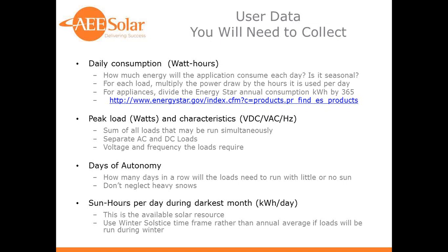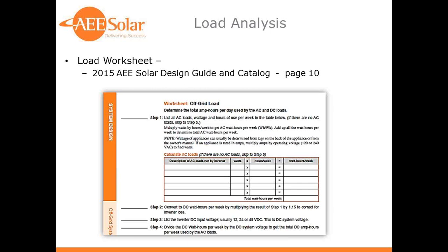So that's real important to do. Now, you may, say in December, decide to actually run the generator more, although running generators is very expensive, and with PV so cheap these days, you really should size the system properly for the darkest month. So there's a variety of ways to do this kind of load analysis.